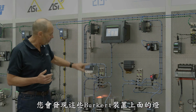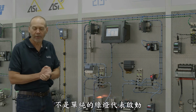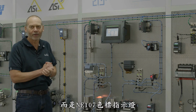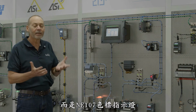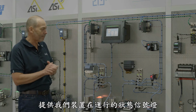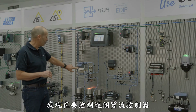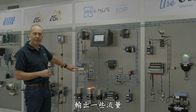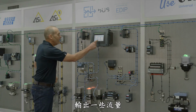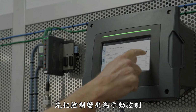To give you an idea of some of its capabilities, you'll notice also these lights that are on all of the Bürkert products. This is not just a green means power on. This is actually a NE107 color-coded bar, which gives us a status indication as to what is actually happening on that device. As an example, I'm going to take control of this mass flow controller here, and I'm going to output some flow. By taking control and putting that into manual control,